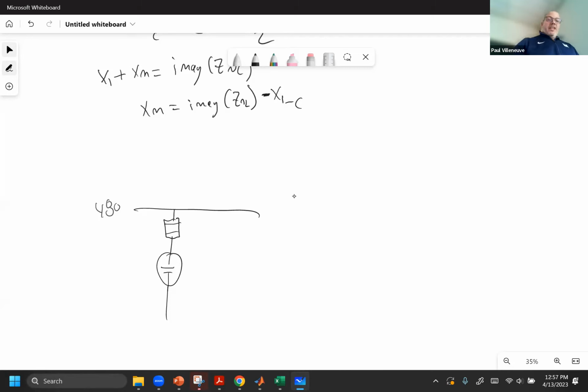One of the things that controls the opening or closing of this contactor is that it steals power off here and does control power. What you'll see is this is typically 120 volt, and you'll have a push button. So you'll have a start push button where you'll hit the button here.